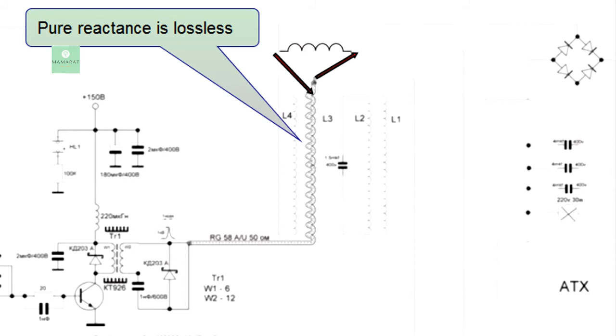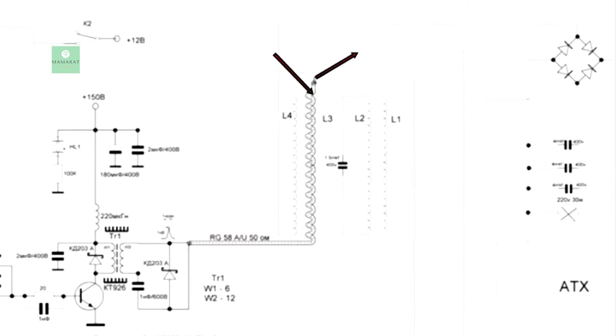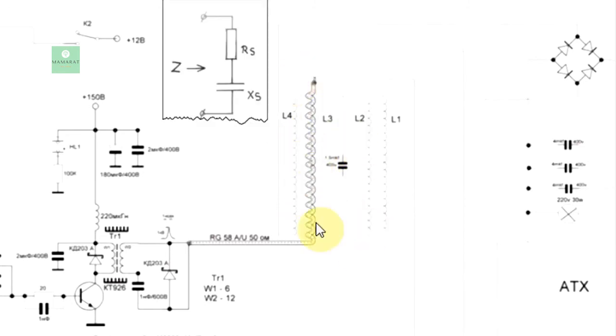It's going to change the wave shape you get on your time domain reflectometer in a very characteristic manner. That once you learn to do pattern recognition, you'll say, yeah, I know what that is. That's a capacitive load at the end of that cable. And by how much it gives you this effect, you can tell exactly how many picofarads of capacitance it's got. So a capacitor must reflect.